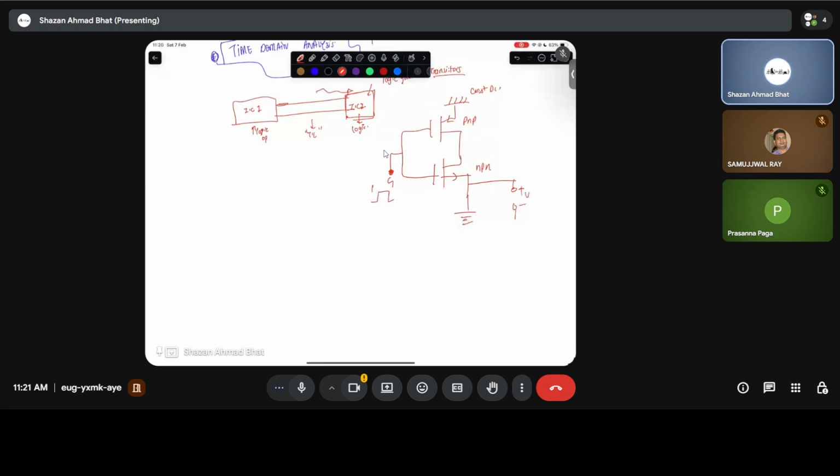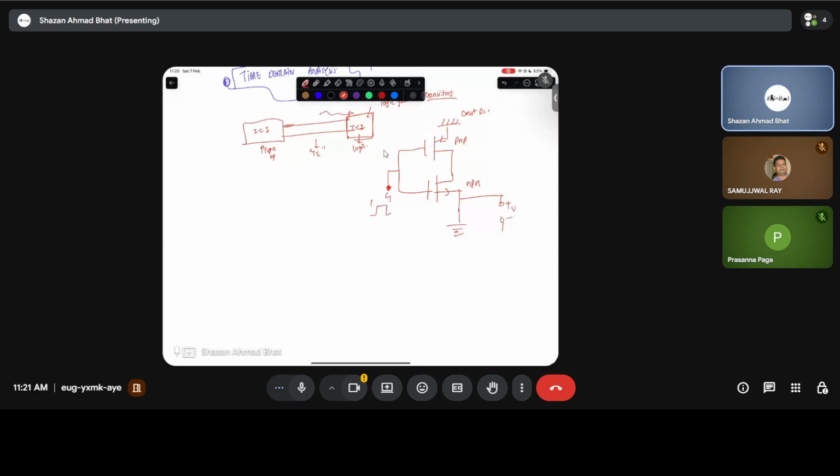So it looks something like this. If this is 5 volt and this is some threshold voltage, if the voltage goes below this threshold voltage, the entire region is treated as zero, which is basically digital zero. Otherwise, it doesn't make sense if you are having zero voltage. Whenever there is binary zero, there is some voltage there, otherwise it will not be able to read, but that voltage is less than the threshold voltage. If the voltage is greater than threshold voltage, it will be treated as 1, and below this it will be treated as 0. So that is a simple scenario of the digital circuits.